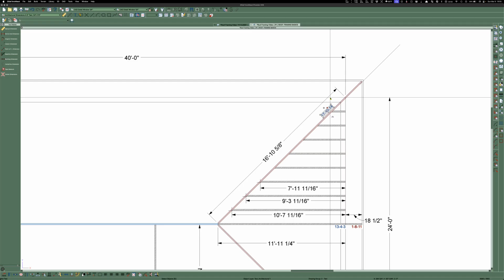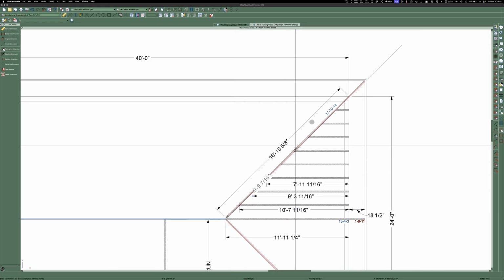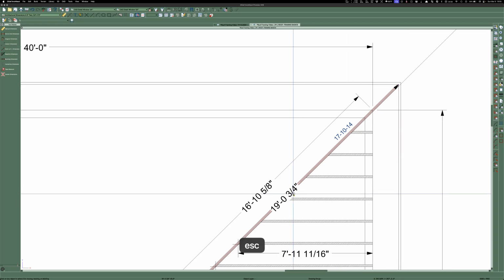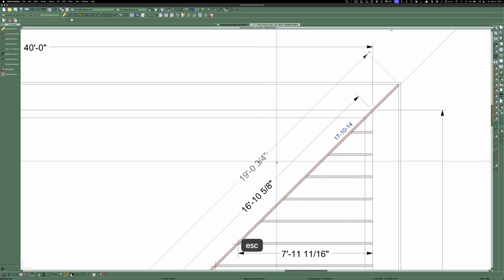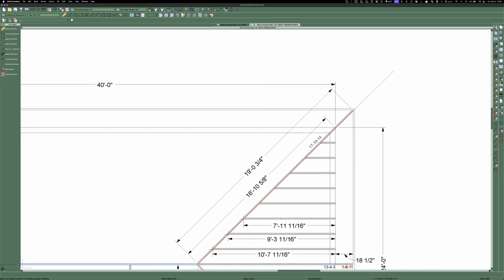But in reality, I'm going to actually cut it all the way out because when you have a common overhang or common pitch, I guess, and the overhangs are the same, then you might as well just cut that hip with a tail that sticks way out there to help support everything. So instead of just stopping here, I would stop here and I would make the appropriate bird's mouth, but then I would carry on and have my tail come all the way out to hold the subfascia. So we can do that.